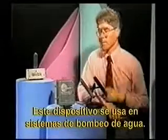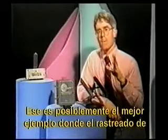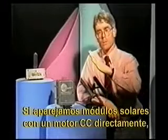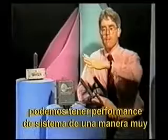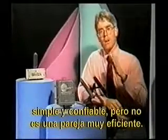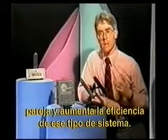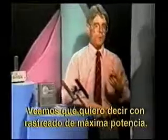This is an example of a device that's used in water pumping systems. That's probably the best example where maximum power tracking gives enhancement to system performance. If we couple up solar modules to a DC motor directly, we can have system performance in a very simple and reliable way, but it's not a very efficient match. This max power tracking device enhances that match and increases the efficiency of that type of system. Let's take a look at what I mean by maximum power tracking.